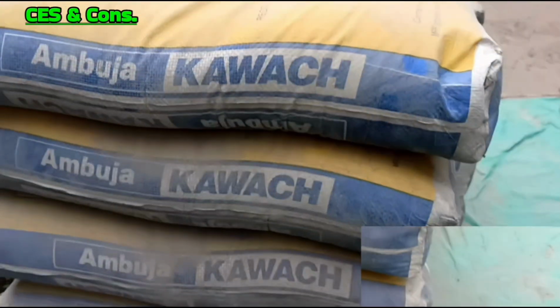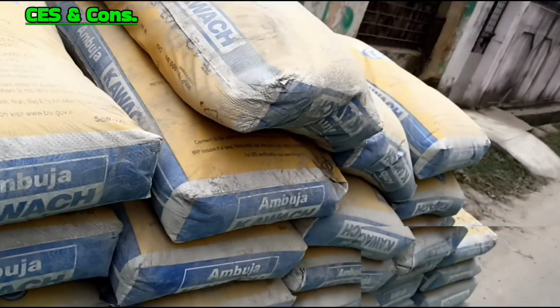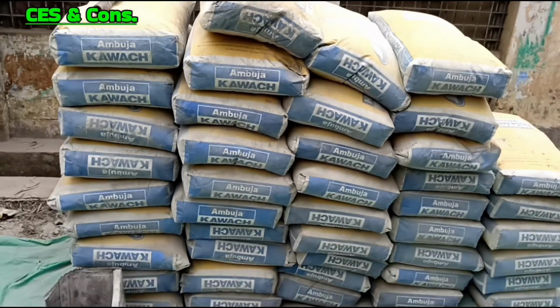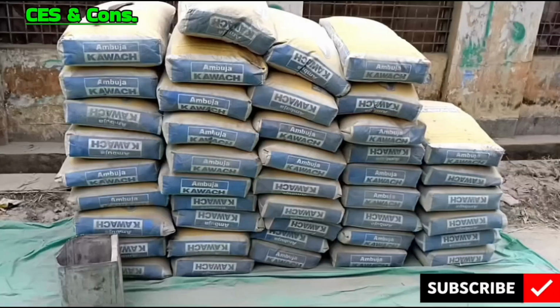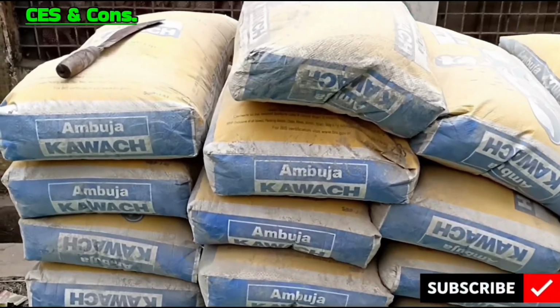Number 4. Soundness. This is as per IS 4031 Part 3. Expansion not more than 10 mm by Le Chatelier method. Number 5. Consistency. This is as per 4031 Part 4. Standard consistency of cement paste should be 26% to 33% water.